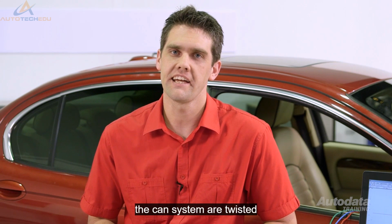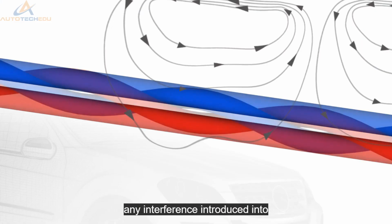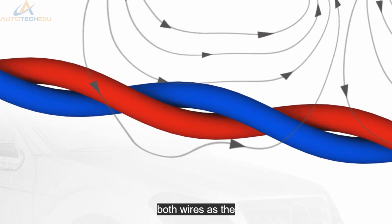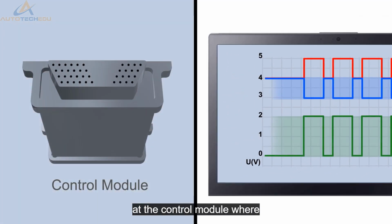The 2 wires in the CAN system are twisted together to help eliminate interference. Any interference introduced into the wires by electric or magnetic fields tends to couple both wires. As the noise affects both circuits equally, it is cancelled out at the control module, where the signal difference is processed.